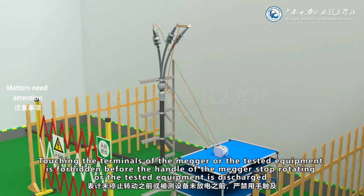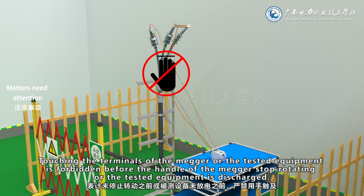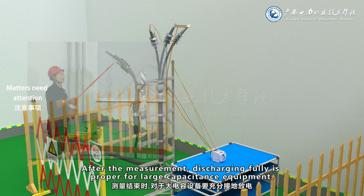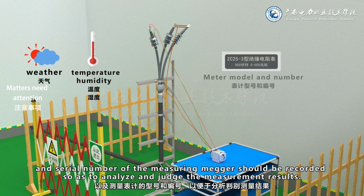Touching the terminals of the Megger or the tested equipment is forbidden before the handle of the Megger stops rotating or the tested equipment is discharged. Don't touch the metal part of the lead when disconnecting the wires. After the measurement, discharging fully is proper for large capacitance equipment. The weather, temperature, humidity and condition of the tested equipment as well as model and serial number of the measuring Megger should be recorded so as to analyze and judge the measurement results.